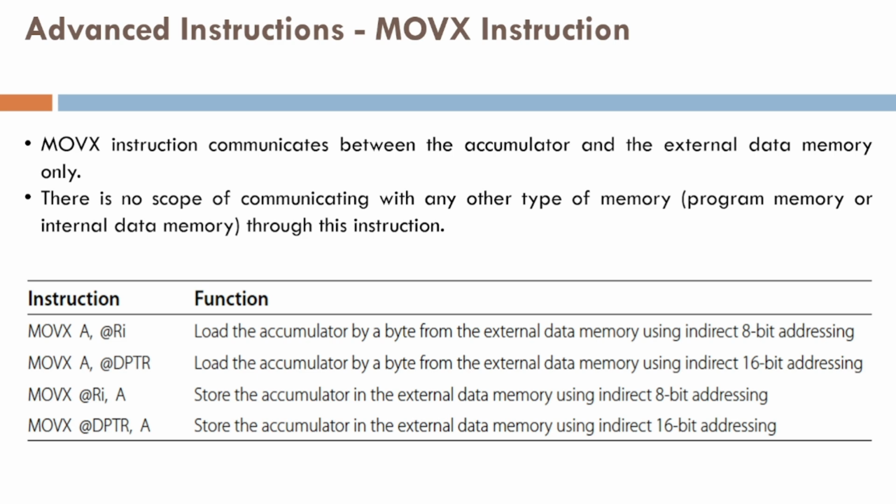You see here, MOVX A, @DPTR is an instruction where the data pointer register already has a 16-bit address available inside it.